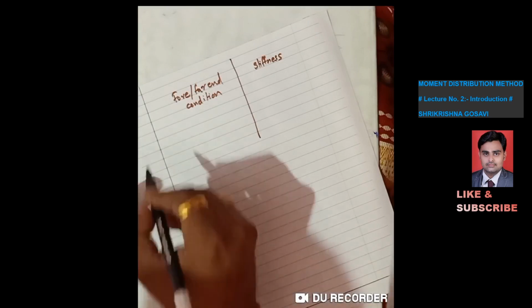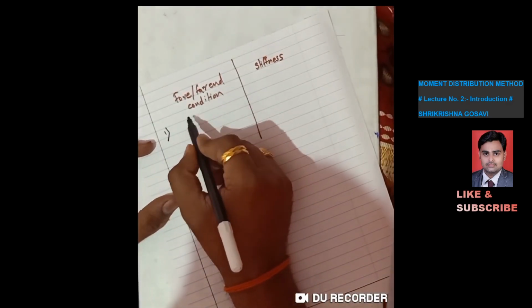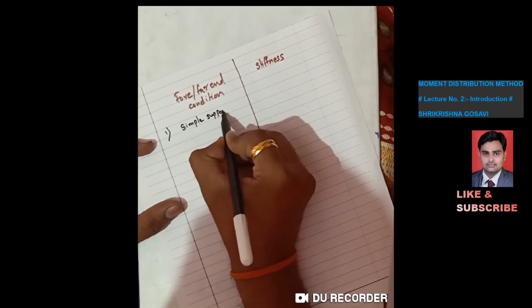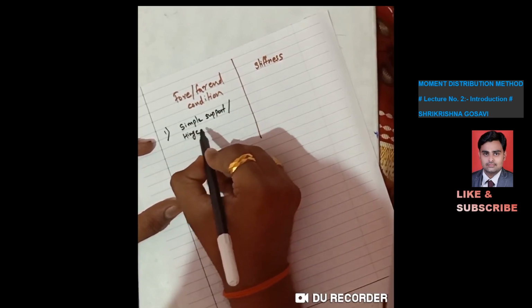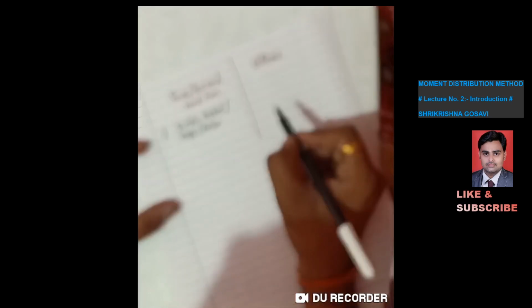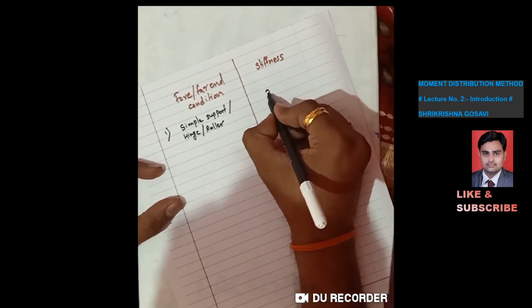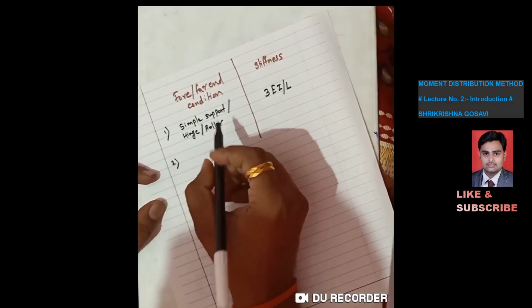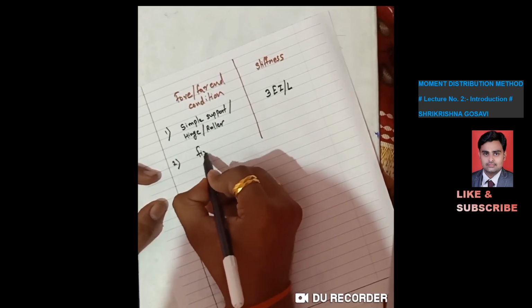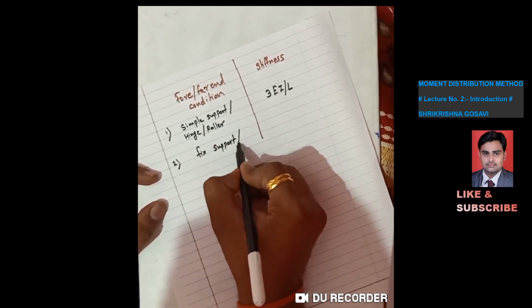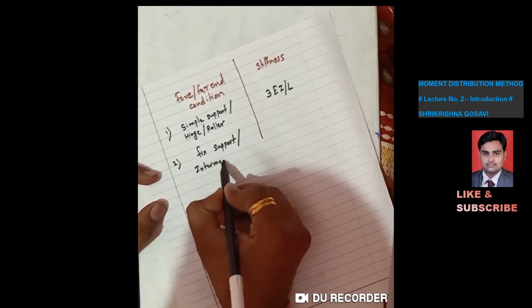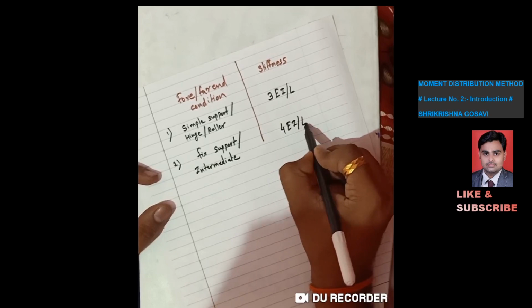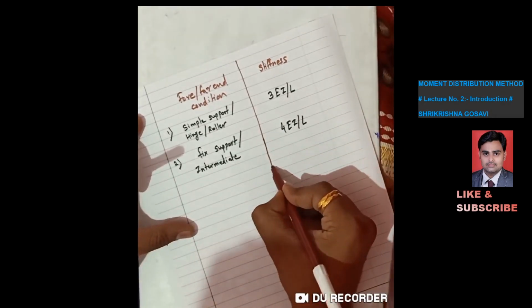Number 1: if your fore end or far end is a simple support, oblique, hinge, or roller support, your stiffness is 3EI by L. Second: if the far end is a fixed support or intermediate support, then the stiffness is 4EI by L.